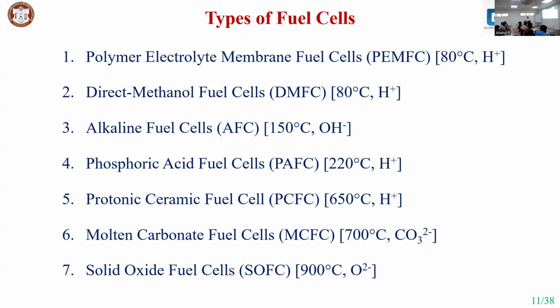How do we eliminate the carbon dioxide without any reaction on the cathode side, because water is already available and the carbon dioxide will combine with water? Carbonic acid is going to be created, and that is going to corrode the fuel cell components. So you need to work out how to recover the carbon, whether you convert the methanol, allow the carbon into the cathode side, or take out the carbon at the anode side and use it for some other application. We need to really work on that.